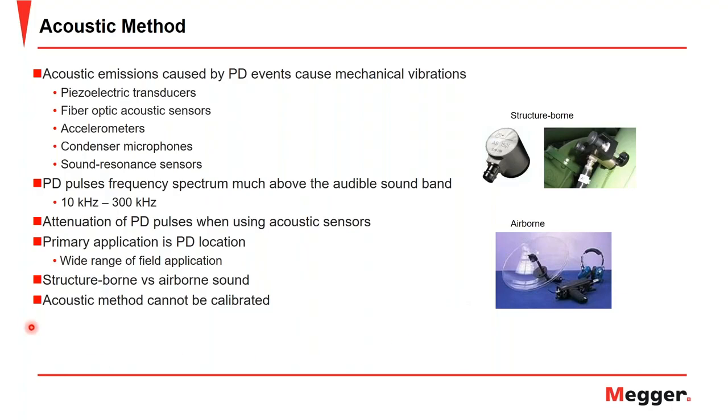And another big takeaway, similar to the electromagnetic method: the acoustic method cannot be calibrated, as there is no correlation with the PD quantity, apparent charge, because a calibration of the acoustic method cannot be conducted to find a suitable reference value.